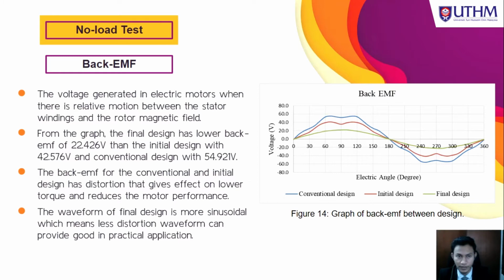Okay, next part of the no-load test analysis is back EMF. Back EMF is the voltage generated in an electric motor when there is relative motion between the stator winding and the rotor magnetic field. Figure 14 shows the graph of the back EMF between the designs, which are conventional, initial, and the last one is the final design.